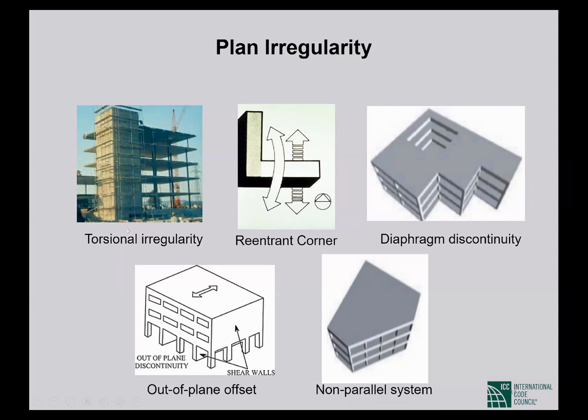Now, they may ask, okay, then can't we have any shear core placed eccentrically? Should we always place the shear core or shear walls in a symmetric way? The answer is no, but if we allow torsional irregularity, in that case, we have to design accordingly. So we'll see later what are the provisions that we have to follow if a building has certain kinds of irregularities.